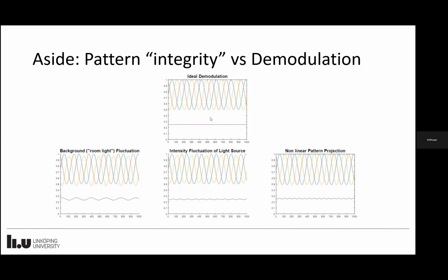For the low-cost system, we just pre-distort. Since we can't get direct access to the DMD itself, we pre-distort our images, so when they are projected, it compensates for the distortion and you get a linear pattern.